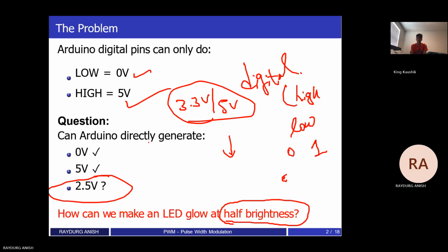Okay. So if you use a resistor, then it's not efficient. A resistor wastes some energy. Yeah, exactly. The resistor gets heated up, and it leads to some losses, but more efficiently we can do it by using PWM signals. And another reason why we keep a resistor is to decrease the current so that the LED won't get burned off.